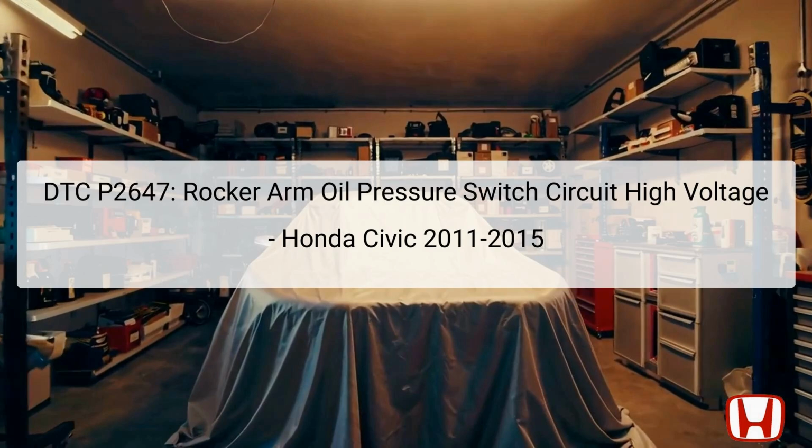The Diagnostic Trouble Code, DTC P2647, indicates a high voltage condition in the rocker arm oil pressure switch circuit on Honda Civics from 2011 to 2015. This system plays a crucial role in controlling the variable valve timing and lift electronic control (VTEC) system, which optimizes engine performance and efficiency. The rocker arm oil pressure switch is generally located near the rocker cover, where it monitors oil pressure reaching the rocker arms.